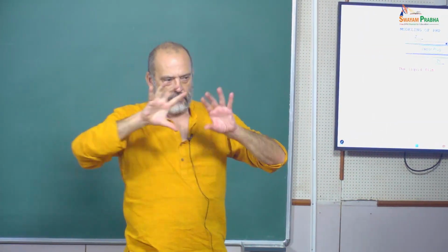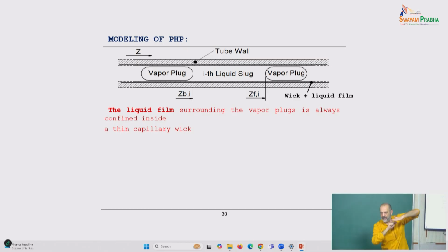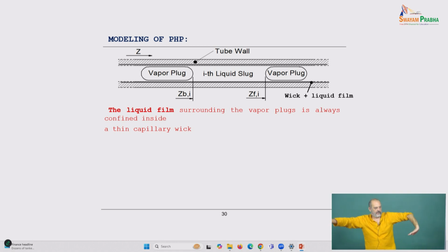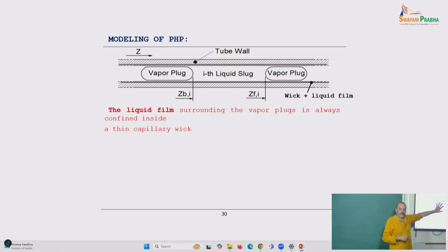Imagine the contrary. Don't look at the vapor, look at the liquid. If you move a surface with respect to another, it's a kind of coating, because you are coating the system. The liquid is staying there, and you are coating the plate or the tube, whatever. So the liquid film dynamics is very important.